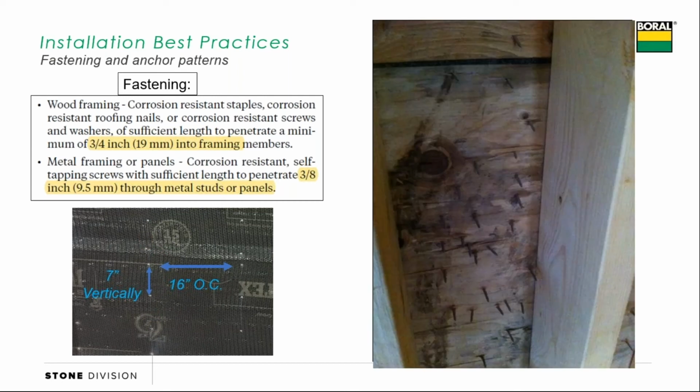All too often, and I can tell you I did it, I took the nail or staple gun and I went to town. Usually that was for a couple of reasons. One, I thought we needed a lot more nails and staples to hold that metal lath on to carry all the weight of that stone system. I will tell you that all of our testing shows that nailed on this pattern is more than enough, or sufficient, to carry that weight. The other reason is metal has a memory, and if there's a bubble in between, we like to go through and put a bunch of nails or staples in to hold that bubble in. The problem with this over nailing and stapling is metal lath with that proper nail pattern is flexible in between these studs.